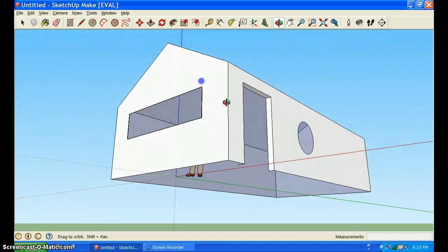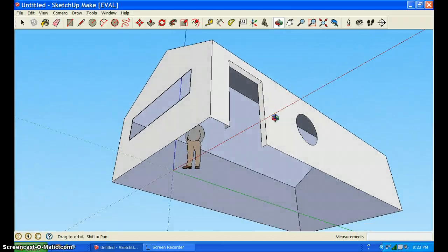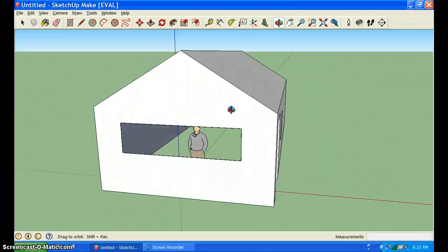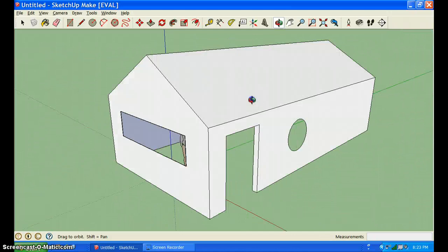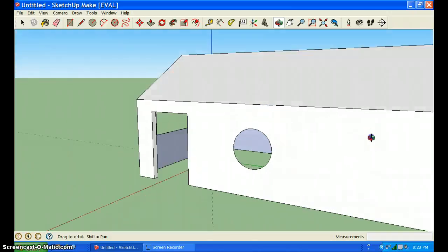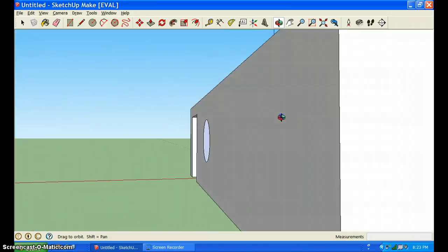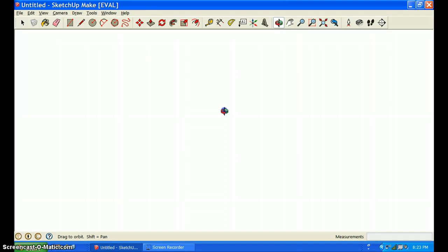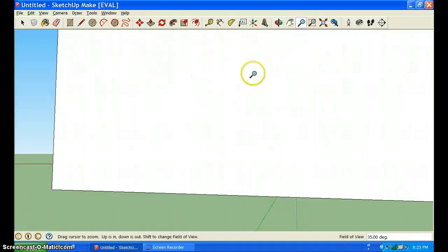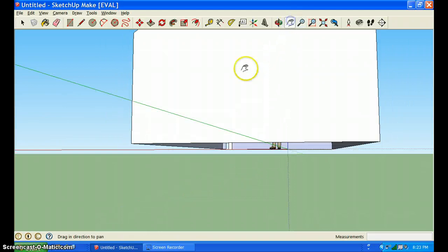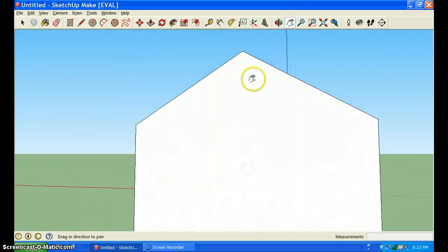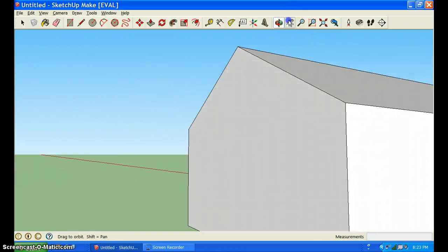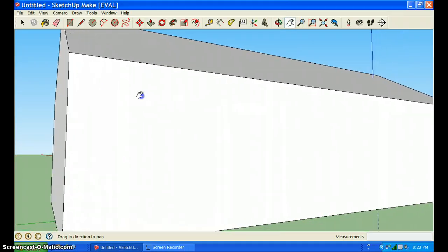Let's take a look inside. Look at that. Oh, amazing. That's all you have to do. And as I go around from the other side, remember, as you turn things around, they can tend to get very close to you. Look, I look like I lost everything. I'm going to use the zoom tool. Zoom out. Use the pan tool to move it. There we go. I'll go around to the back of the building with the orbit tool again. Pan tool, move it over. Zoom tool.